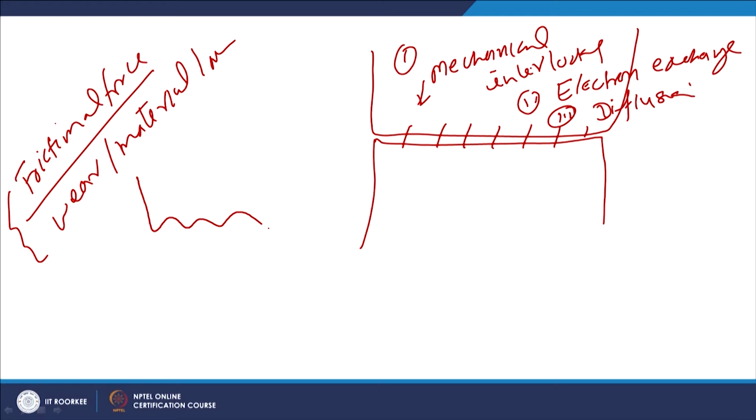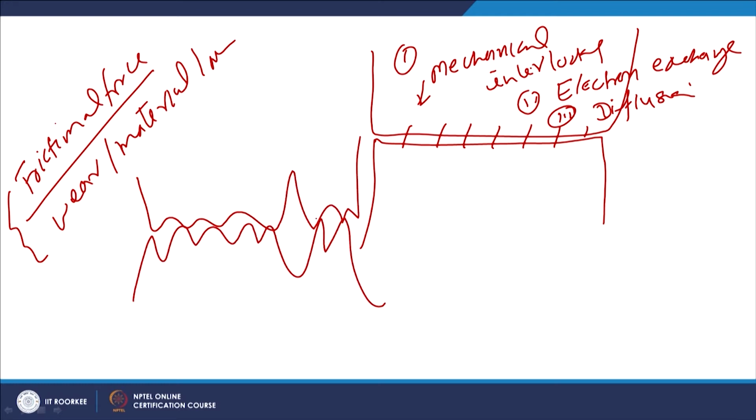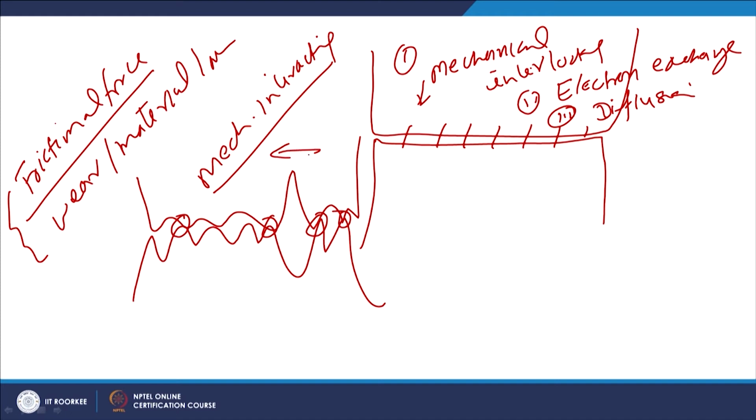What is important, since all surfaces have surface irregularities, the contact exists at very localized points where true stresses are very high. So, the surface layer deformation takes place, which leads to the mechanical interlocking. Greater the mechanical interlocking, greater will be the force with which two components will be holding together, and accordingly it will require greater force to maintain the relative movement.